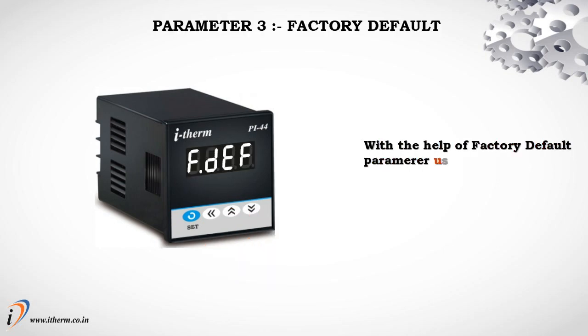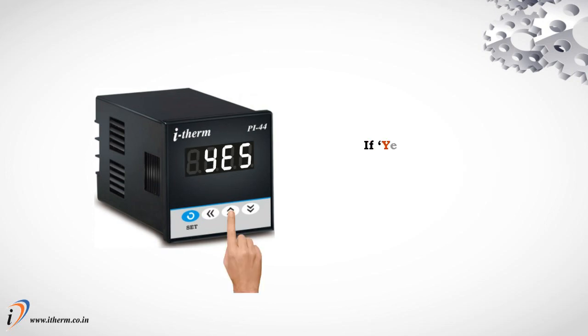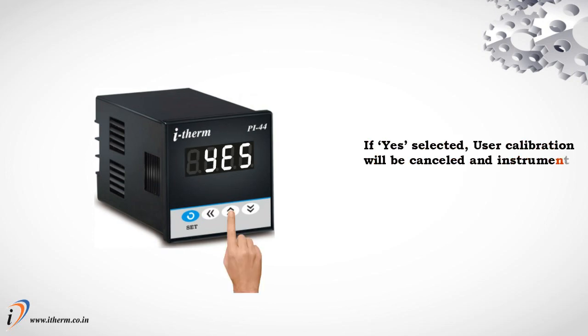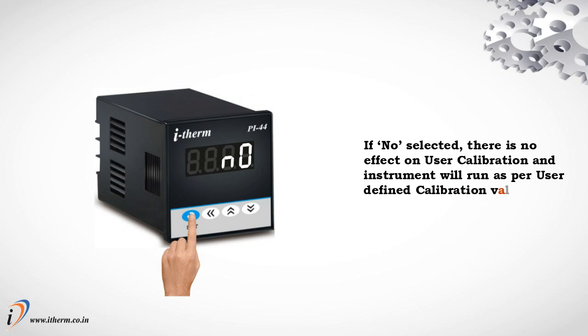Parameter 3, factory default. With the help of factory default parameter, user can cancel out user calibration and factory calibration will be loaded. If yes selected, user calibration will be cancelled and instrument will run on factory set calibration values. If no selected, there is no effect on user calibration and instrument will run as per user defined calibration values.